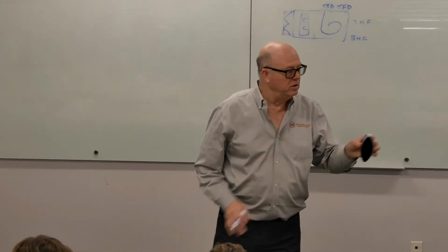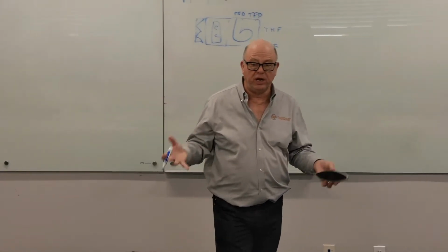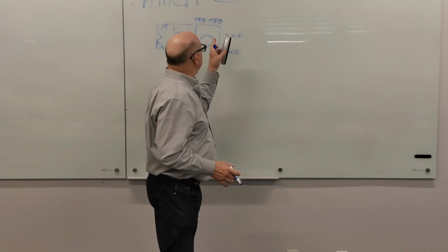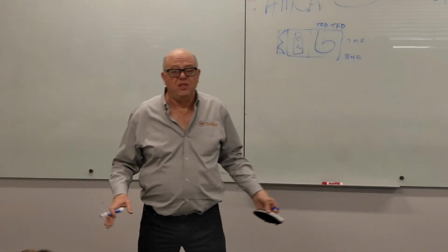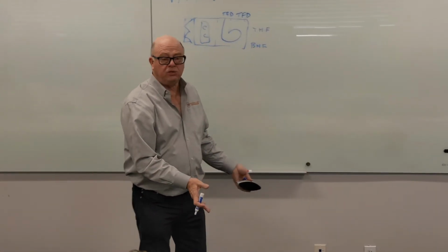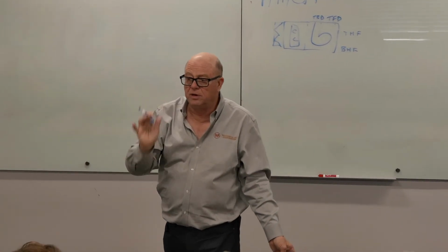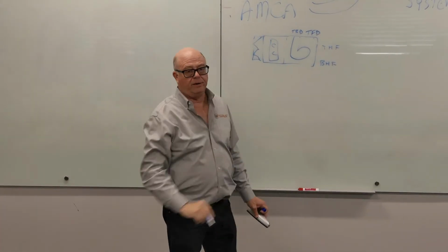This is another design thing, and it's another submittal check thing. Most consulting engineers not only don't know this, they don't specify it, and they don't show it. They just show the air handling unit, hopefully with the right dimensions, sitting in the room, and they leave it to the contractor and the equipment vendor to figure out which discharge do I get.